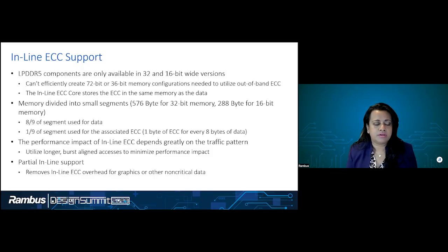However, in the LPDDR5 case, you will see that it is not feasible. For the out-of-band ECC to work, say for instance, you have 64-bit data, you would require 8 bits of ECC in that case to give you a total of 72 bits.